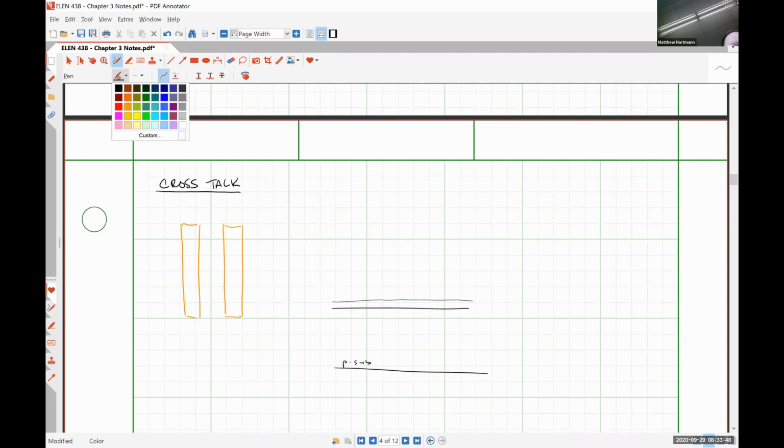And that insulation will be all of the different insulations that we need until we reach our metal 3 layers, where we would have something that looks like this. And these aren't floating off the top of the substrate. I'm just trying to give it a third dimension so that you can kind of see what's going on here. So we have those metal wires laying on top of the substrate.